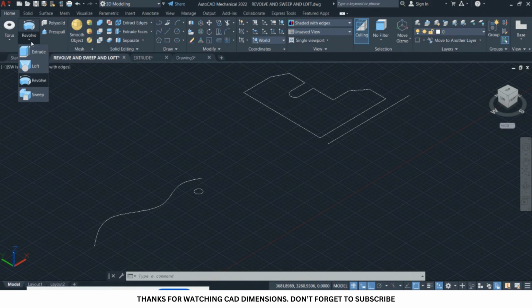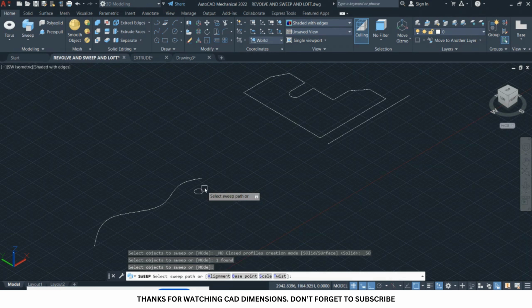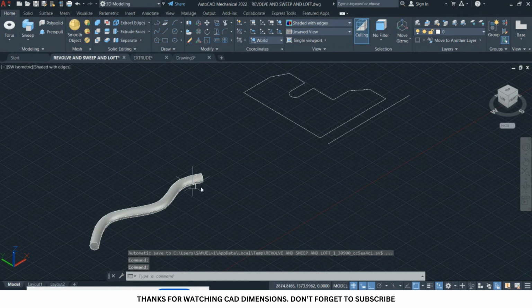For the sweep, you need to have an open sketch and you also need to have a closed one. So this is the open sketch I'm talking about, and this is a closed one. You pick the shape that is closed and then you apply it to the sketch that is open. So the first thing you do is you select the object, press enter, then you select the path, then that particular circle is applied on the open one. All right, so that is with respect to the sweep.